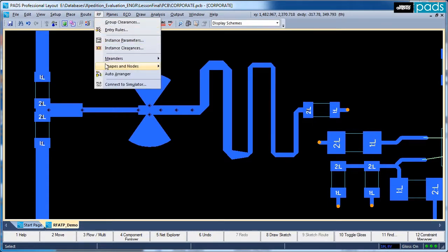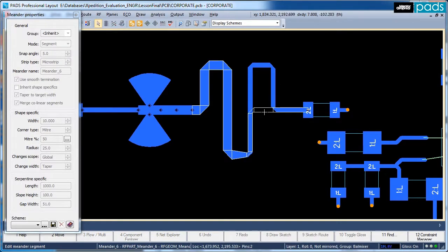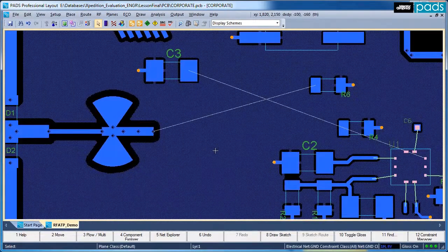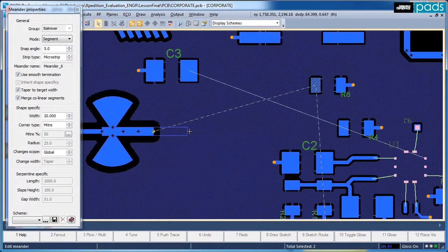To interactively edit the meander, invoke the Edit Meander command and move segments as you like. When moving segments over each other, the command will snap them into place and remove redundant segments. The Edit command also provides options to lock bends during the edit operation, to allow seamless editing of meanders at arbitrary angles. The meander uses the same clearance handling as all other RF elements.